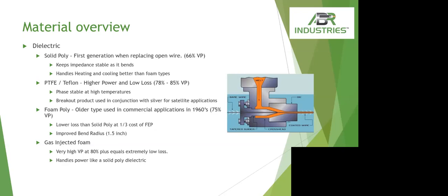So when you think about this for HF applications, if you're running the legal limit, there's a lot of heat that will be generated. You may want to look at RG213 just because it'll last longer than sometimes the gas injected foam dielectrics. The next is the Teflon products, PTFE, higher power and lower loss, a little bit different velocity range,